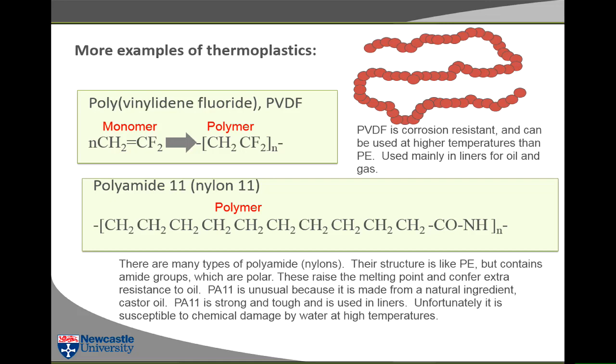But when it comes up out of a well, oil has water in it. Sometimes it has water in it naturally, but quite often it has water in it because you put in injection water. You have injection wells where you inject the water, which pushes the oil towards the wellhead. So the older the well is, the more water there is in the oil which comes up.